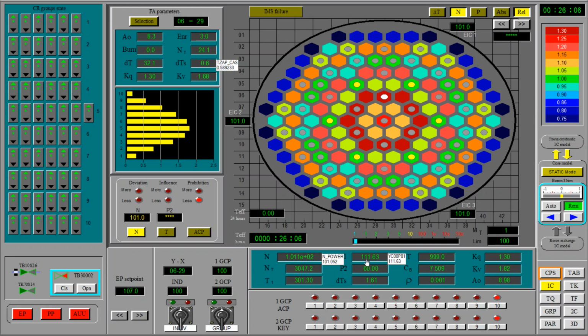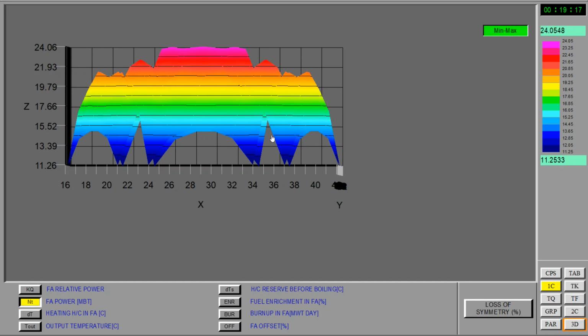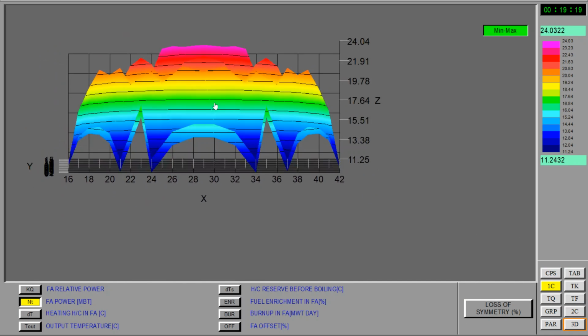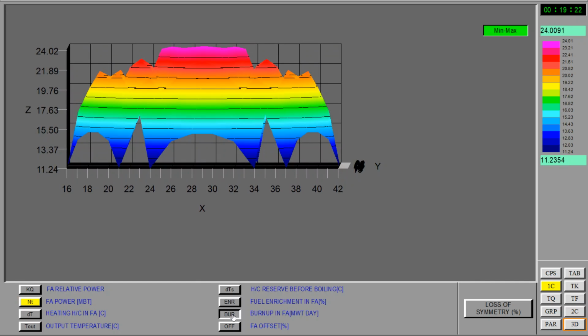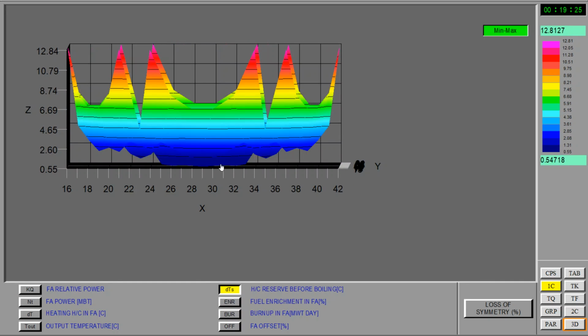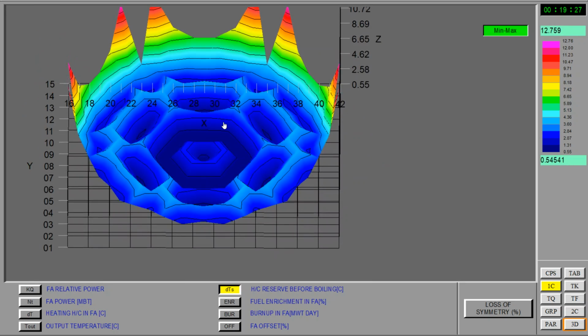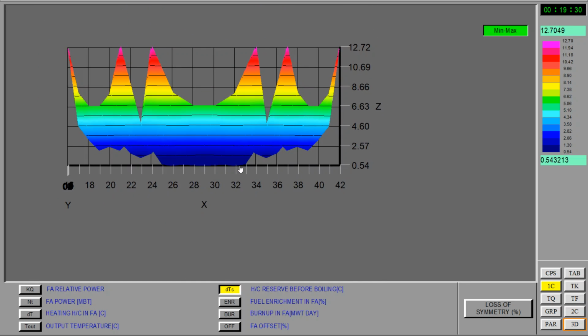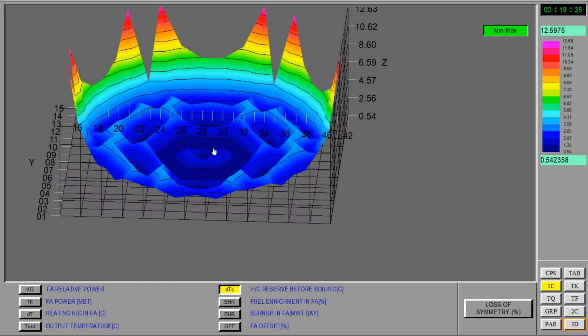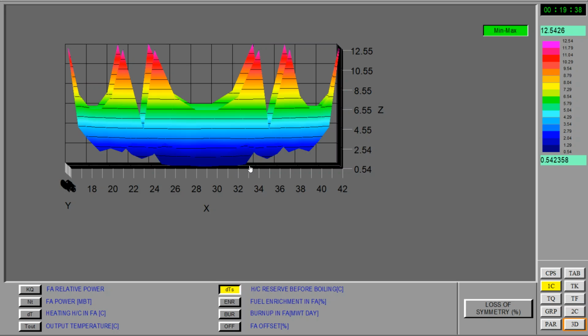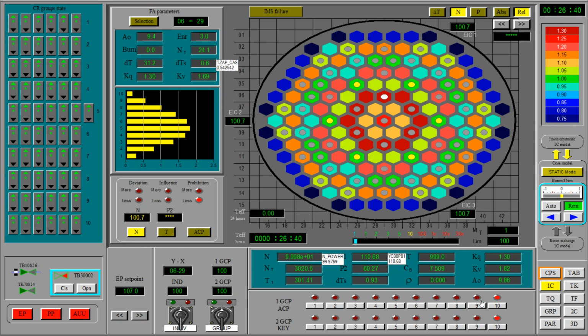Okay, and the pressure is really low now, it's 111 bars. I wonder how is it possible that we still keep decreasing pressure and keeping power, and we don't see relevant changes anywhere in the 3D plots. Now it really seems that the reserve before boiling is getting closer between this region and the high activity region. Let's decrease more boron.